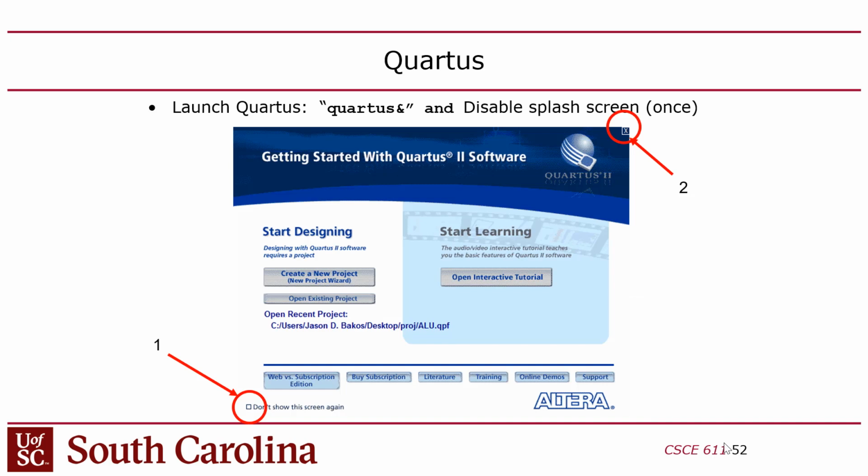Okay, so then we've got Quartus. ModelSim is where we simulate. Quartus is the tool that will synthesize and interacts with the physical hardware. So once you're satisfied that your behavior is correct, then it's time to bring it into Quartus, which will do two things. It'll guarantee you'll meet your timing spec, and it'll synthesize your Verilog onto the FPGA. It deploys it, and it'll make it appear. It'll basically take your logic circuit and cause it to materialize into reality. It'll become something tangible, a real tangible circuit.